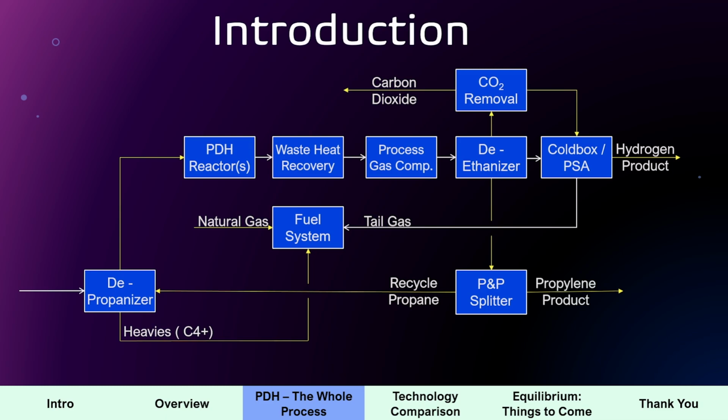They are like methane and ethane and stuff like that. Hydrogen, that's a whole different story. The hydrogen product that you're making is going to be highly dependent on where that chemical plant is located. If I'm located in a chemical hub close to a refinery, they will probably buy it from you at whatever spec you need, probably low spec, because in refineries you normally use it for hydrotreating or applications that don't require high purity hydrogen.